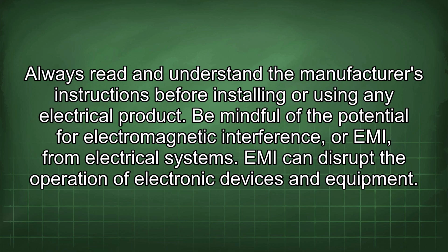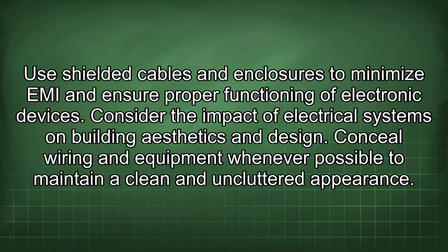Be mindful of the potential for electromagnetic interference, or EMI, from electrical systems. EMI can disrupt the operation of electronic devices and equipment. Use shielded cables and enclosures to minimize EMI and ensure proper functioning of electronic devices.